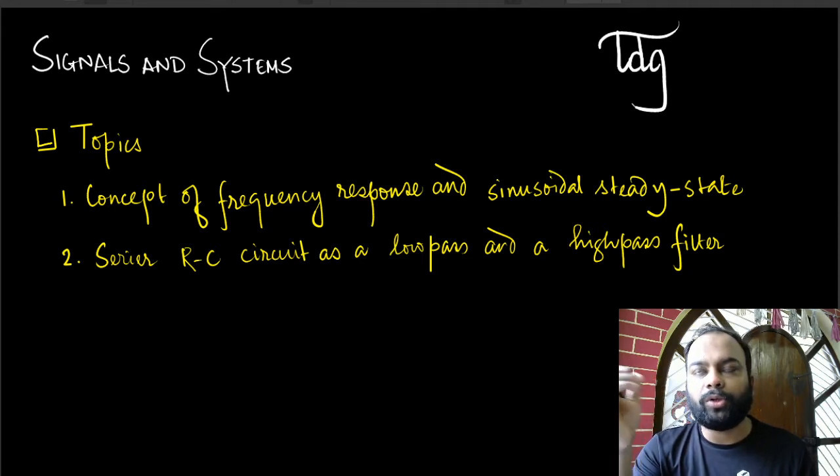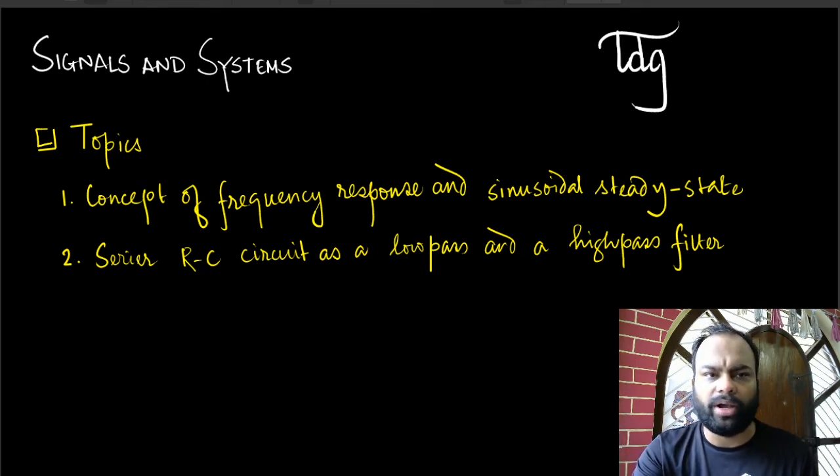So when you studied circuit theory, you did something called sinusoidal steady state analysis, where the power supply would have been an AC and you calculated the impedance of the circuit, and accordingly you calculated the voltage across the elements and current through certain elements and such. What you actually did under the hood was apply Fourier transform on the circuit itself, right?